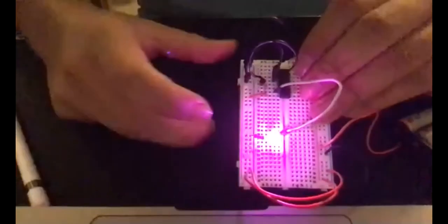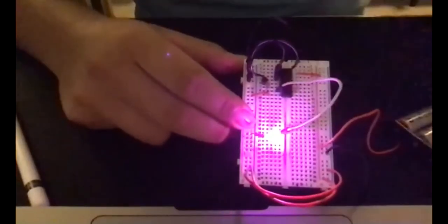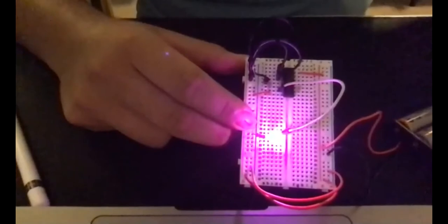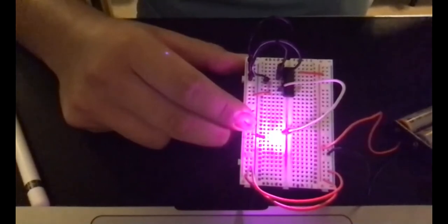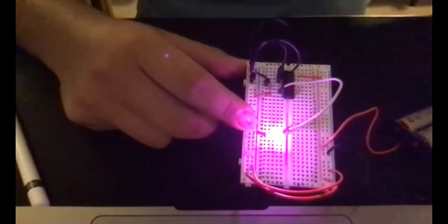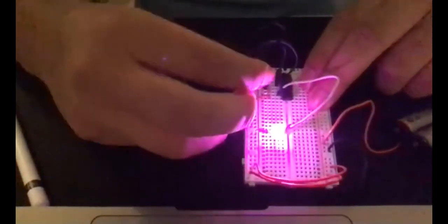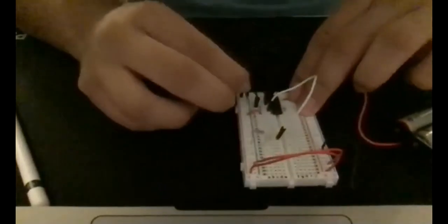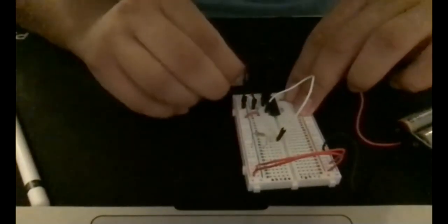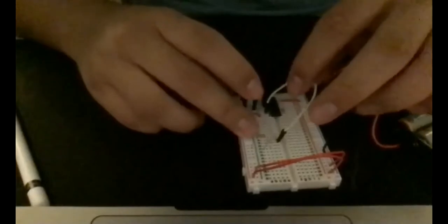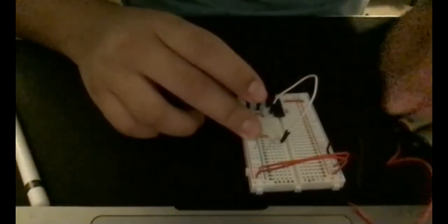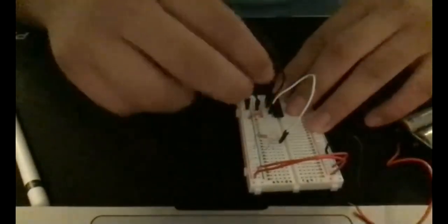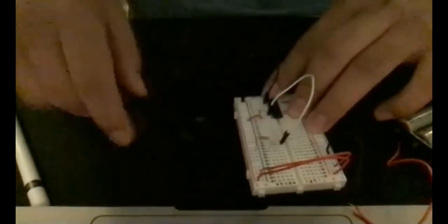So this is because NAND gates can be used universally, meaning you can use a NAND gate to create an AND gate, an inverter, an OR gate, and even a NOR gate. So just to keep running through a little bit more of the simulations now, if we disconnect power here and we make a couple more connections, we should be able to see an OR gate, if I remember this correctly. Should be something like this.